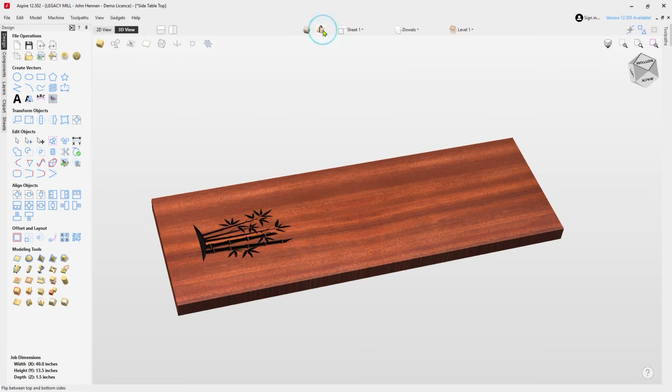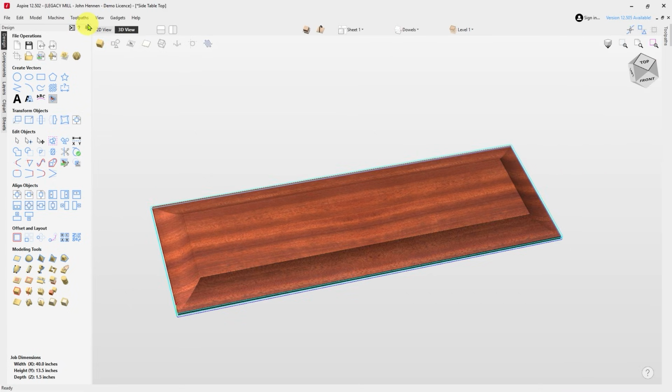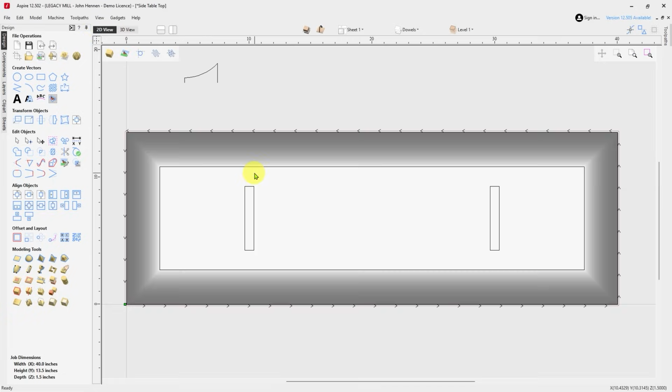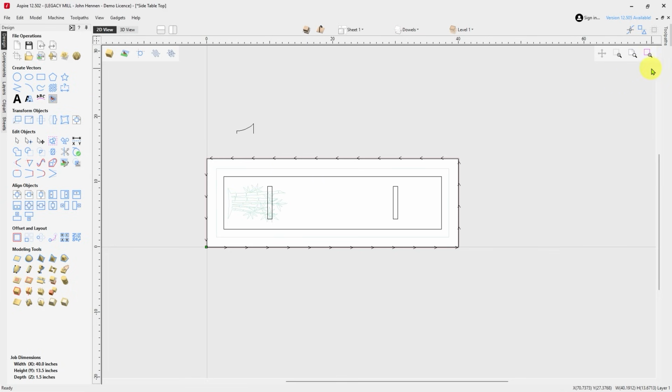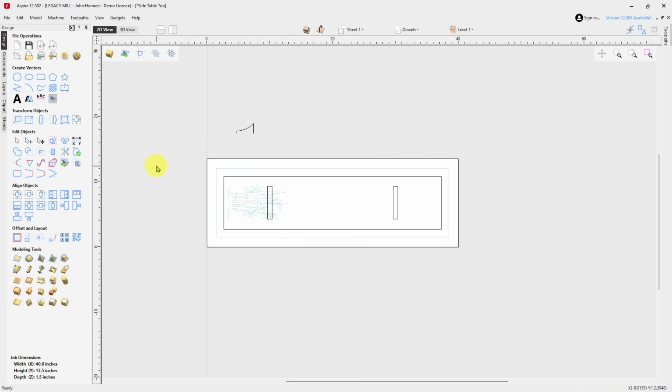On the other side of the tabletop, what we did here is we made a couple of 2-rail sweep. Well, actually, we just made one 2-rail sweep and a couple of pockets, and we were done. This was an easy tabletop to make. Let's go through designing out the 2-rail sweep. Go ahead and delete this original one here, and we'll turn off this toolpath just so it's not in the way. To make a 2-rail sweep, I just go down here to the 2-rail sweep tool.